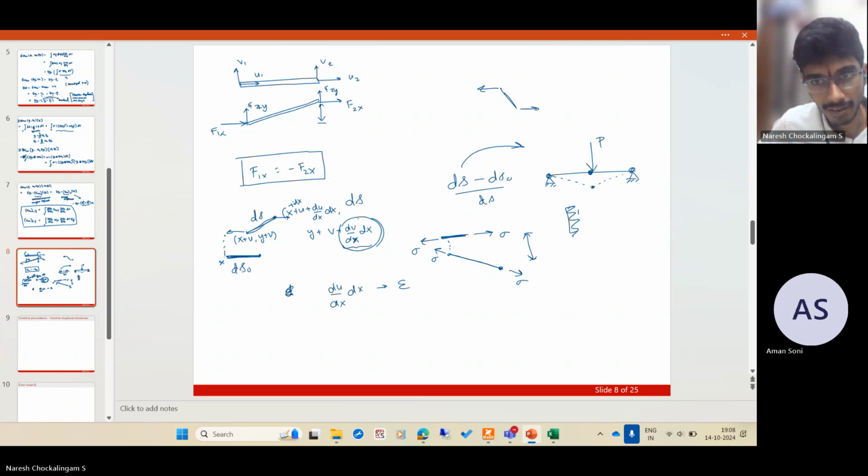So if we don't consider this, okay, so suppose you have P. It's like you stretch a rope between 2 points, and then you hang something from the rope, right? So that is what this is. The stiffness in the rope comes from, so this is an axial force member. Basically, this is an axial force member. If you look at it in a linear elastic sense, it's not possible to keep it in equilibrium, because you have forces acting upwards at both the points, and this is really not possible. It's not possible to keep it in equilibrium when the member is horizontal.